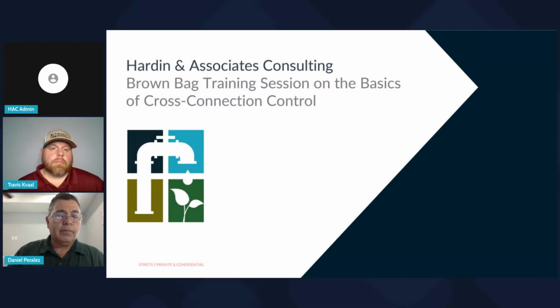Got it. Thank you so much. Another question we have here is what is an LSL inventory and why does a water purveyor have to do it? So your lead service line inventory is being mandated right now by the TCEQ. It's due October 16th. What we're doing there is seeing, both on the public side, the water main to the meter, and on the private side, what our service lines are made out of. And if they're lead, then they're being marked over time for replacement.